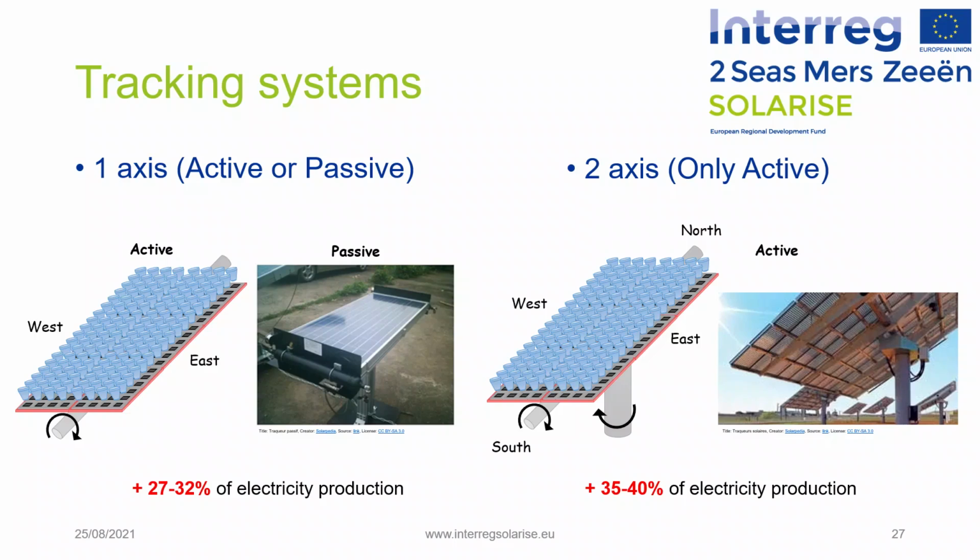And the passive trackers that do not consume energy but use a specific device that contains a compressed fluid with a low boiling point, which evaporates into a gas when heated up by the sun, that adjusts the equilibrium of the CPV system. Nevertheless, these passive trackers are less accurate than systems focused on light detection technologies, and they require manual intervention to optimize the north-south direction depending on the season, as they are not designed to be dual-axis.